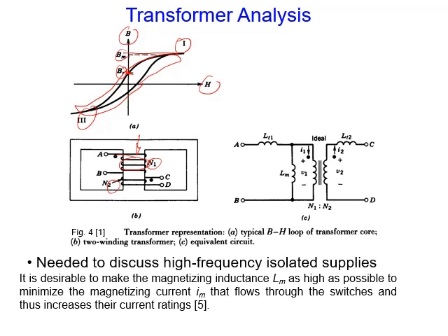And if we represent it and consider the magnetizing inductance LM, it is the inductance here. This is the input voltage, output voltage. Usually in the design of this high frequency transformer, the magnetizing inductance is as high as possible to reduce the current, because at the end it is acting as a current choke.